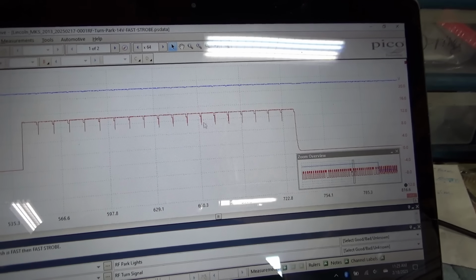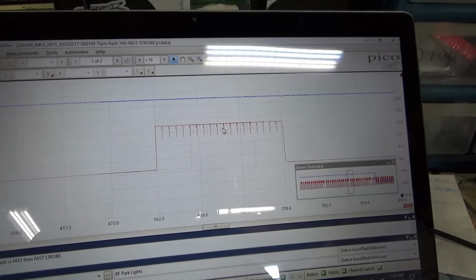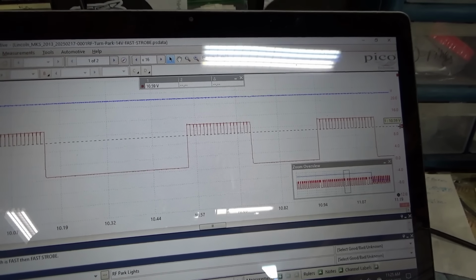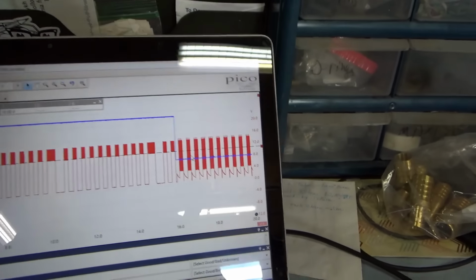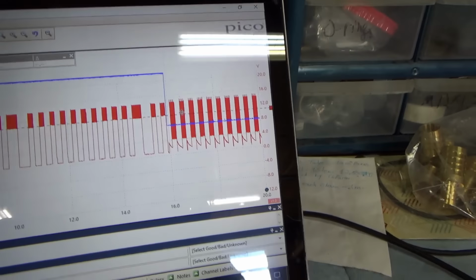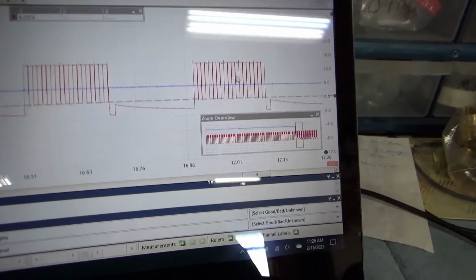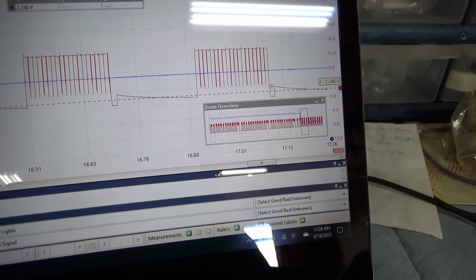But look what's going on at the tops of these pulses. What is this? This little, like, what is that? And these things are dropping out, the little mini pulses, dropping down to about 10.5 volts. So this is a fast flash, and then when you turn the parking lights off, the light show begins. Strobe action. I guess today we're dropping to about 4 volts on the little spikes, and then the ground is that same kind of a hump ramp down, not to ground at all. Starts at about 3.5, goes down to 1.5.